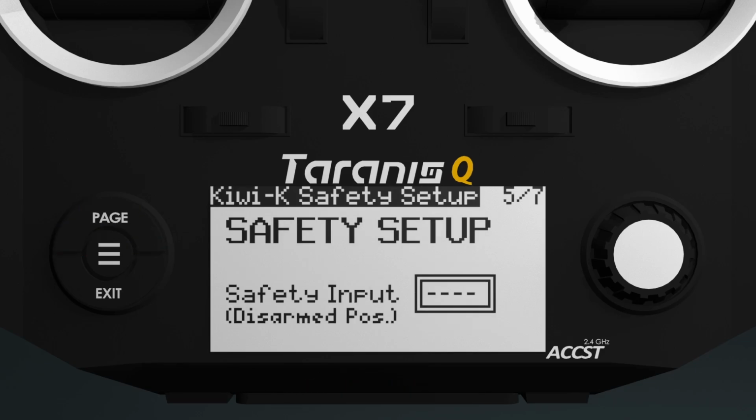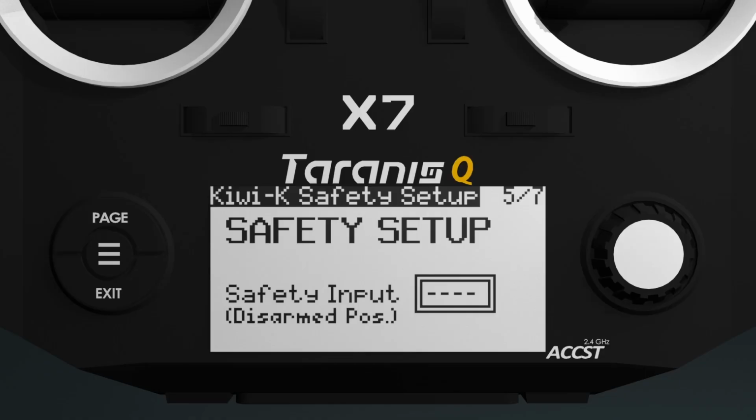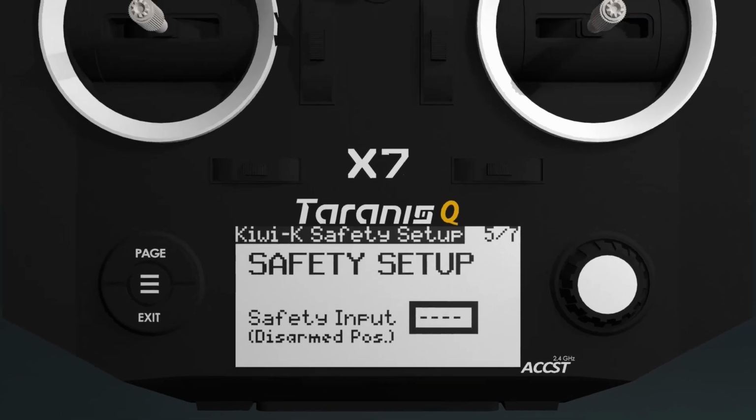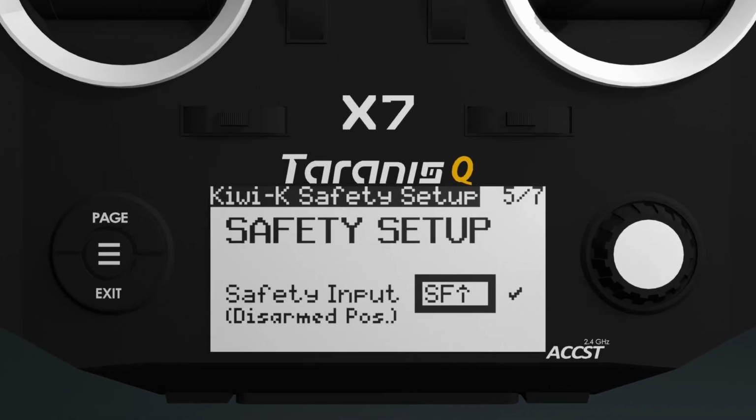Now, we'll set up the safety switch for the robot. If you have a weapon, this will help prevent you from accidentally turning it on while loading and unloading from a test box or arena. This will prompt you for a switch, so we can move any one of those to select our input. Whatever position you leave it in will be the disarmed position, and to arm the robot, you'll have to move it away from that position.